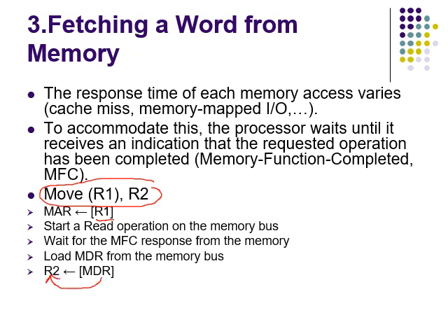These actions may be carried out as separate steps, but some can be combined into a single step. Each action can be completed in one clock cycle except action 3, which requires one or more clock cycles. That is, action 3 is waiting for the memory function completed, which takes one or more clock cycles depending on the speed of the addressed device. For simplicity,